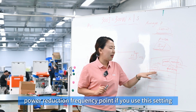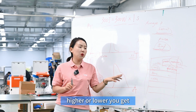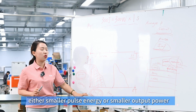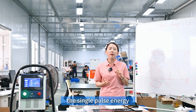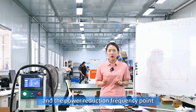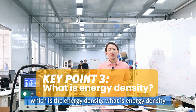If you use this setting, you get the highest power, highest pulse energy. If you change the frequency higher or lower, you get either smaller pulse energy or smaller output power. So after we make it clear about the power, the single pulse energy, and the power reduction frequency point, we come to another very important definition, which is the energy density.